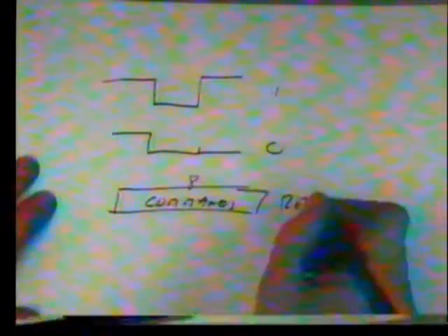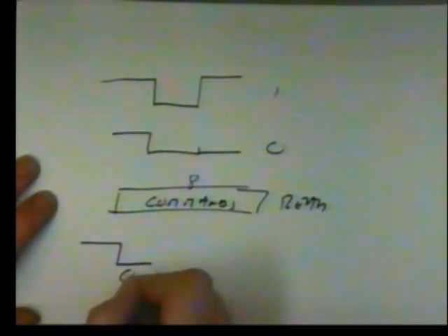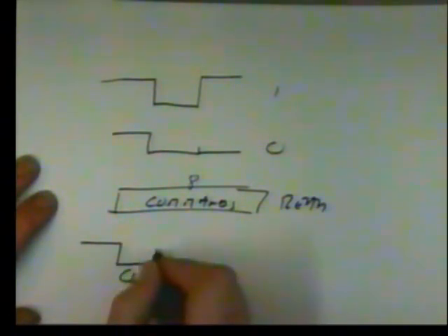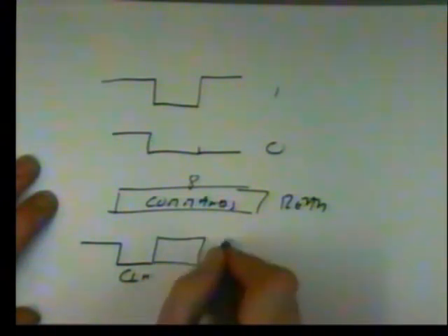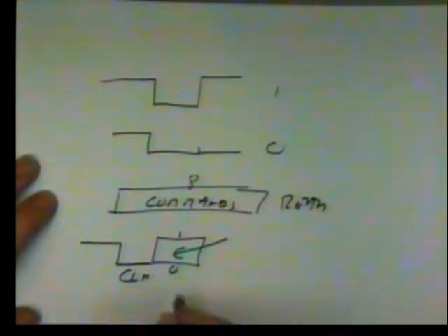8-bit commands, bytes, and then if the command is a read operation, all that happens is, if we were trying to read, the master would output a clock signal, and then it would read back in a 1 or a 0 from the slave device.